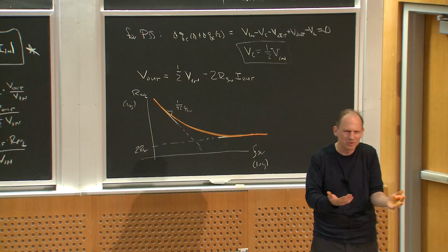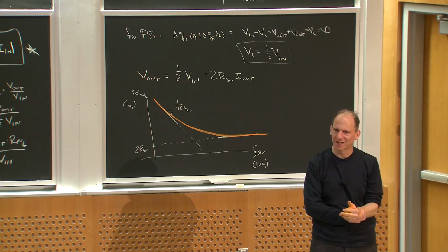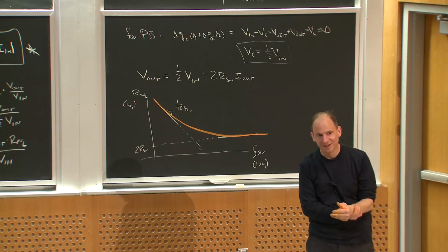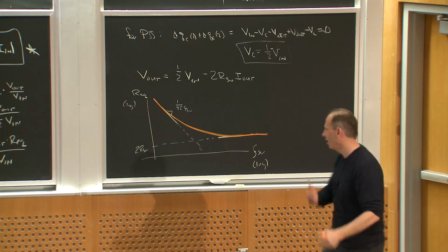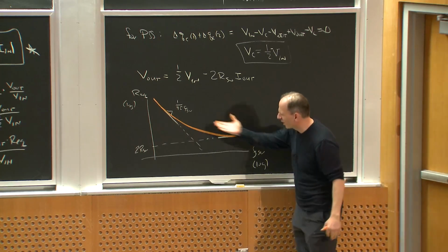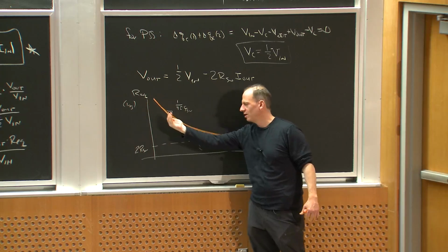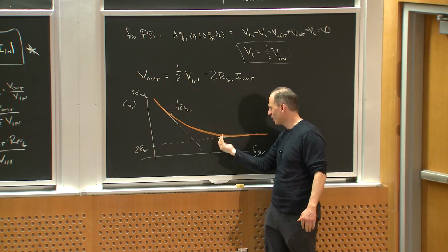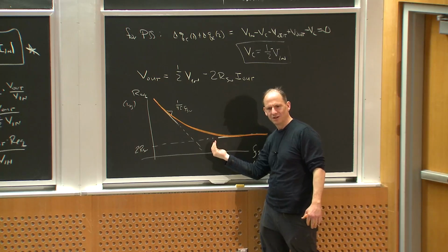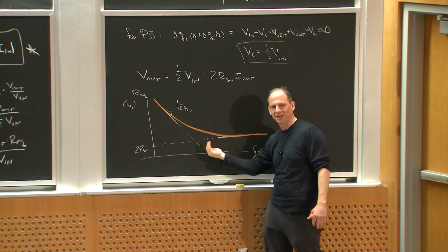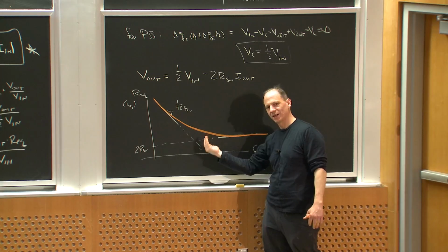Well, if I'm charging through 2 switches all the time, I've got to eat the on-state loss of those switches, right? I can't have 100% efficiency. But if I'm using 10 milliohm switches, maybe that's pretty damn low, right? So essentially what I would tend to do is keep turning up the switching frequency until I get down into this regime where turning it up any more doesn't reduce my output resistance. Because at that point, there are other losses like gate drive losses which get worse with frequency. So I ought to just go high enough that I can get to very high efficiencies.